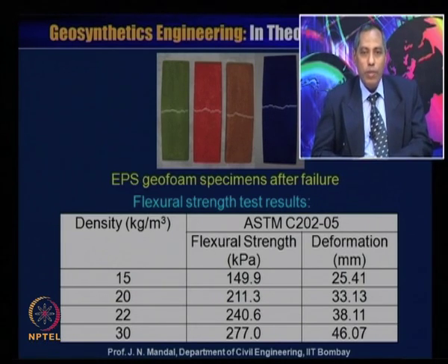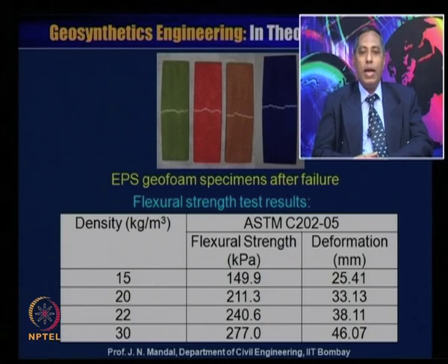So, from this table it has been observed that the flexural strength increases with increasing density. It lies between 149.9 and 277 kilopascal. Deformation also increases with increasing density of the expanded polystyrene geofoam, and lies between 25.41 millimeter and 46.07 millimeter.